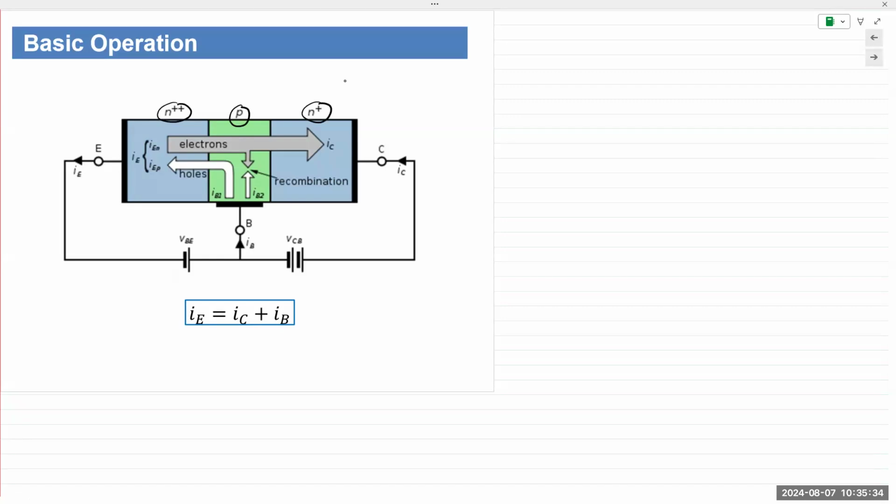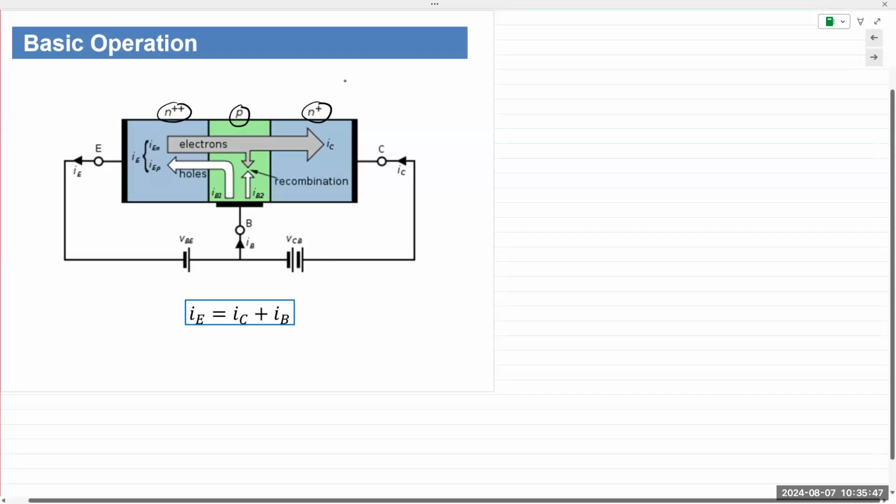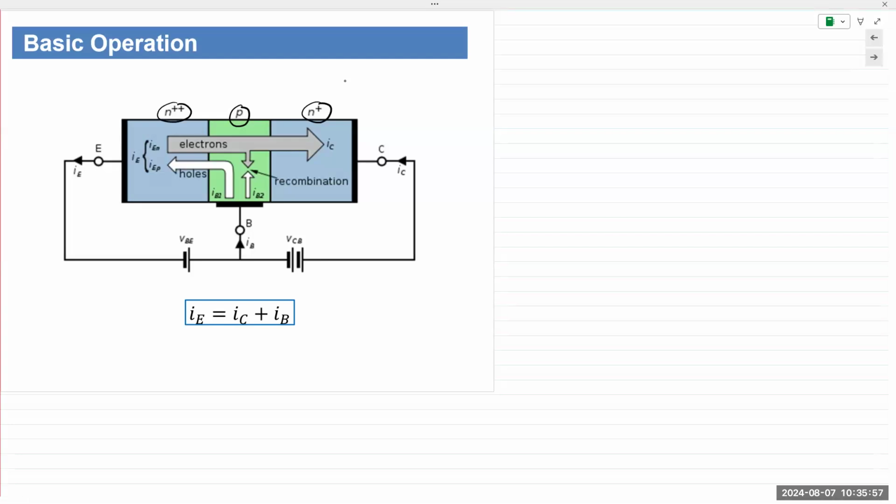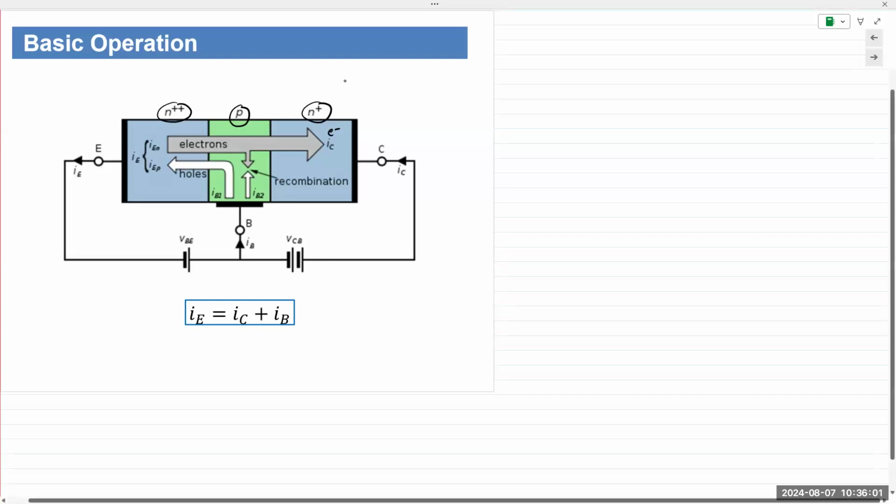Physically, it's very thin. Plus, it is lightly doped, so it doesn't have as many free charge carriers. And because it is a p-type material, that means it has holes. And then you have the N plus, meaning it's a level above lightly doped and quite a few levels below heavily doped. And it's an N-type material, so you have electrons here, and you have positive holes here, negative over there.